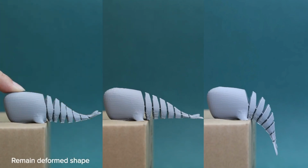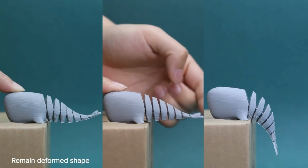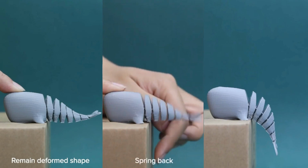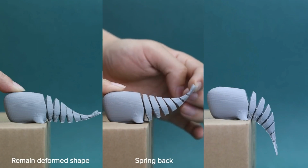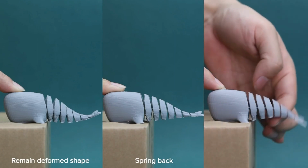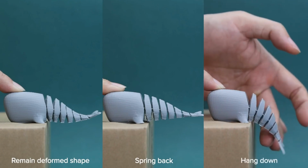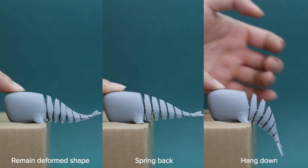With medium extrusion, longer bridges would be elastic in a certain range, which keeps the objects bouncing back just like a spring. With the minimum extrusion parameter of 70% and a minimum printing speed, thin and long bridges are no longer stiff enough to resist gravity.